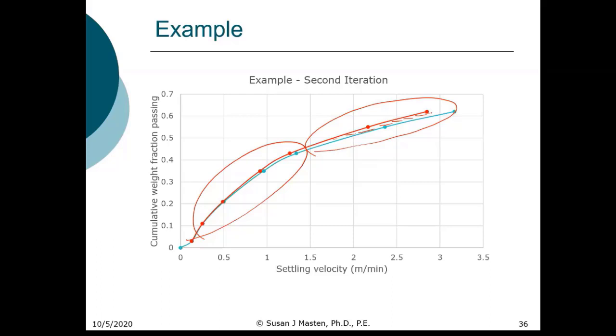It becomes more important when we talk about filtration hydraulics, as you'll see there, because you have to be very, very careful with your backwash flow rates, because you don't want small particles actually leaving the basin. So you'll see there, the iterations become very important. For these types of calculations, one iteration is really sufficient.